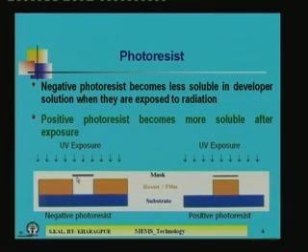Now, you see the mask: there is a black portion here, this line is a mask, and similarly here the black line is a mask. Through that black portion the ultraviolet light cannot pass. The blue layer is the substrate and the red is photoresist or any other film which is sensitive to radiation. If you expose negative and positive photoresist coated substrates side by side using ultraviolet light with the same mask, the pattern will be different.